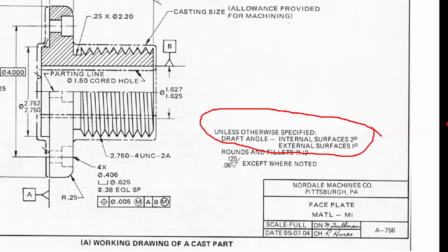So this is called a sprue, and that gets cut off and sanded and thrown away or recycled. But every injection molded piece will have that. You can see what's called the gate where the material comes in. You'll see the parting lines. And if you look really close, you'll see those little circles here, there, and yonder. That's where those ejector pins hit that part while it's still a little bit soft and push it out. So you'll see that on every one of the injection molded parts.